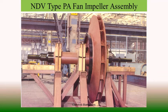For ID fan, the arrangement is double suction type mostly, and radial fans. As there is double inlet and radial discharge, you will find that inlet guide vanes are placed at both side suctions, or rather than inlet guide vanes, there are suction dampers, and on the discharge side also we have dampers.